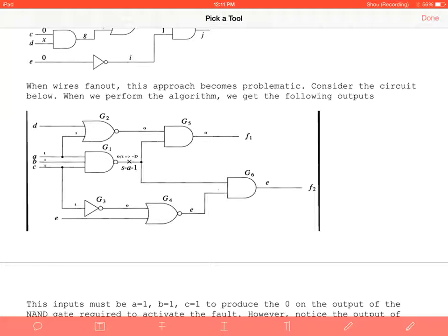But the whole goal is you're going to be learning, okay, I'm going to put together a NAND gate in this tool. I'm going to actually use Spice to simulate IV curves like we learned previously. I can use some Verilog to build up a circuit. The end goal is you're going to be putting a Verilog MIPS processor, making some minor Verilog. You're going to have it fabricated, put it in a pad frame, and do tape out.